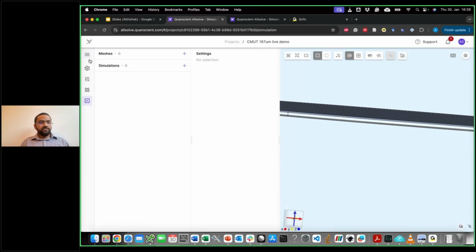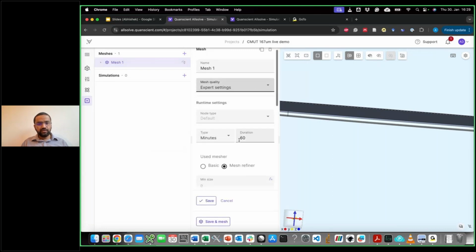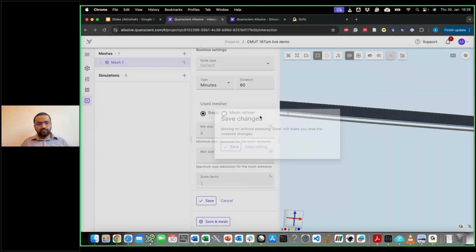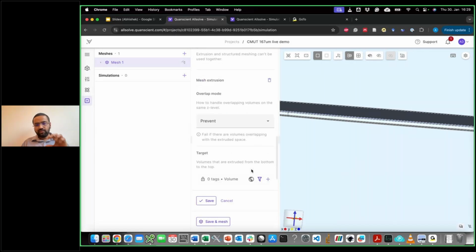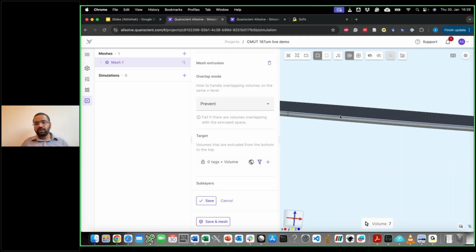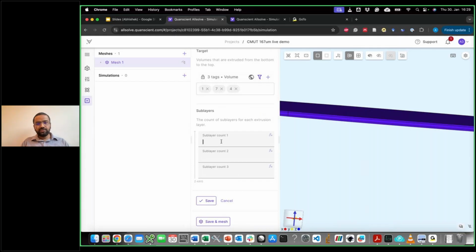Thanks for the question, by the way, and let's have a look now at the setup of the harmonic balance itself. Before that, we have to create the mesh. Let's create that quickly. I'll just go with the basic settings, and as I mentioned, these are thin geometries in terms of the dimensions in the z direction, and typical MEMS devices always have such thin dimensions.